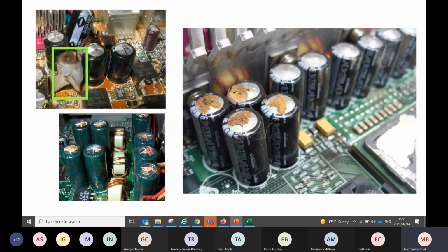And you will see here, that is why capacitors are cut with X's. These are pressure relief valves. When that electrolyte starts to boil and they explode, like this cap exploded, it doesn't explode sideways, it blows to the top, like a little rocket ship, and it blows the cap upwards. But these pressure relief valves open to release steam because the aluminium foil has got so hot it starts boiling, steam, all because of low voltage, okay, and/or an impedance issue on one of the supply cables.